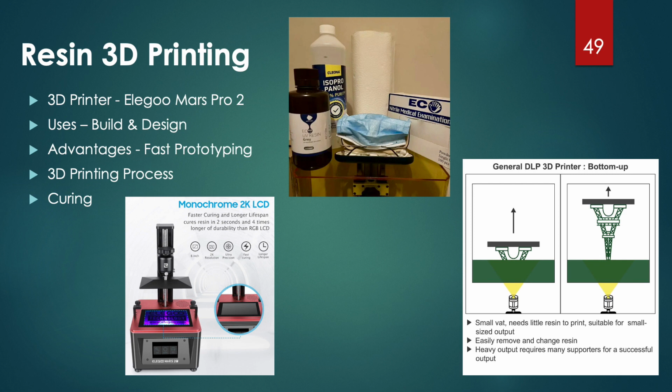This 3D printer technology is a little different than your ordinary 3D printer. Liquid resin 3D printers have higher resolution, which means better detail. It is greater detail because it uses stereolithography technology. You can see the picture to your right showing a printer printing layer by layer. It will project an image, and each layer it will cure with a UV light till eventually you see an object. Print times can take anywhere between 1 hour to 10 hours depending on how big the part is.